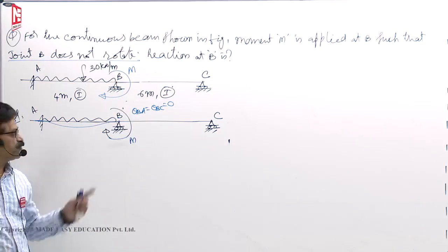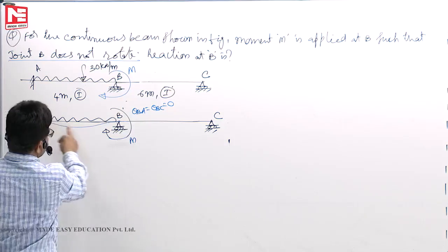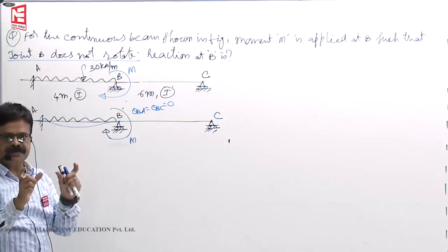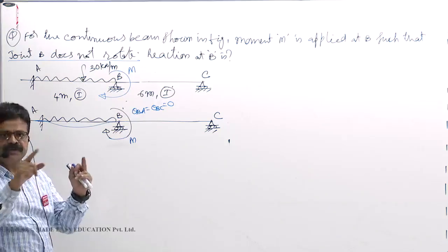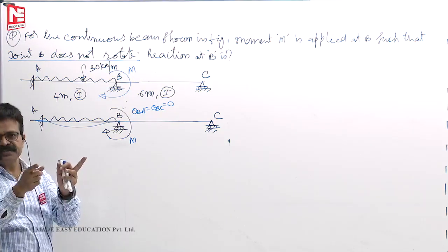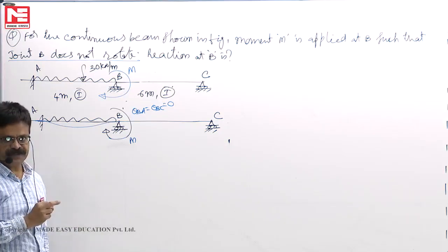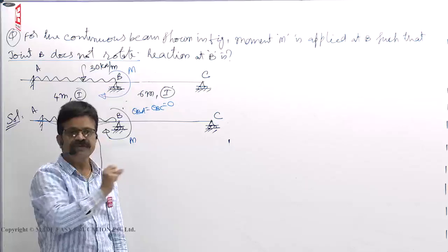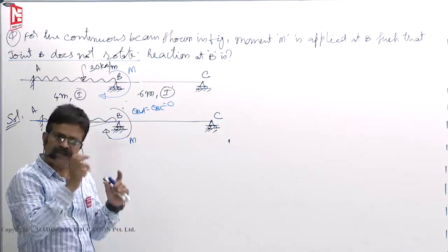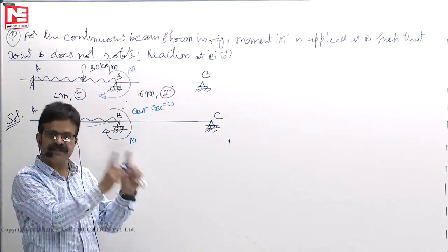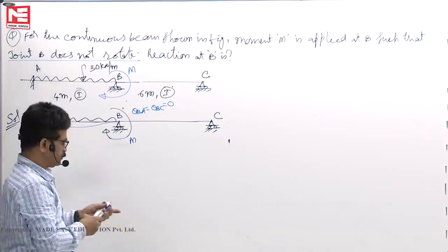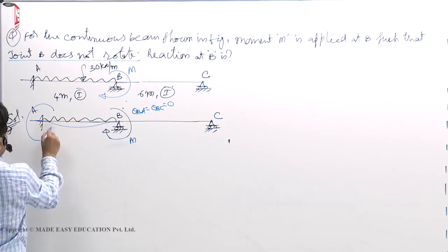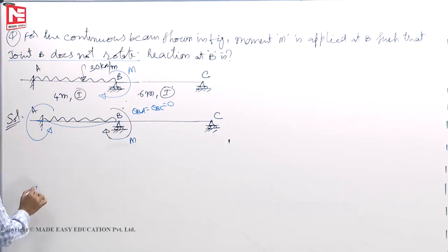Now this deflection profile will tell you that this profile is like a fixed beam profile. A fixed beam, both ends fixed, let us say UDL is there, then fixed end moments also will develop. That profile is similar to this one. Then whatever you have studied about that deflection profile, simply attach them. Now we know what the fixed end moment is. Here how much it should develop for this profile.